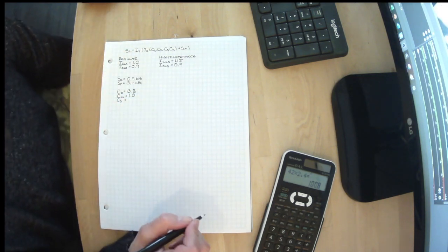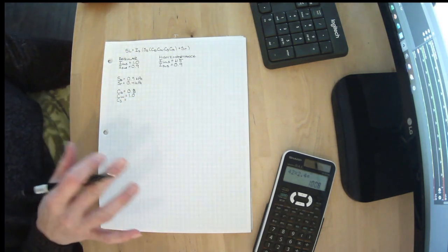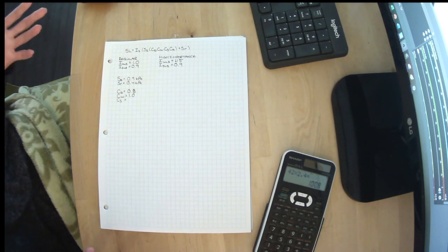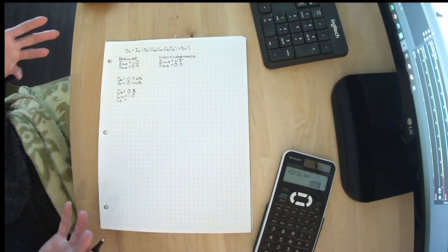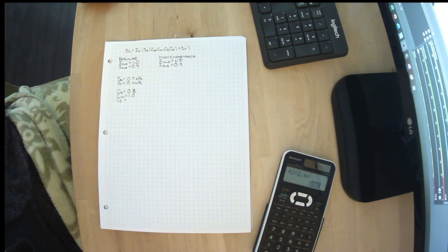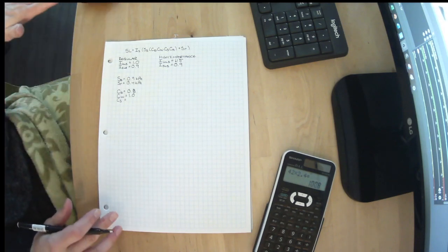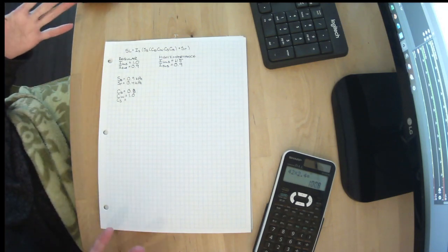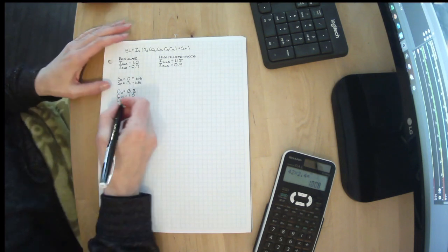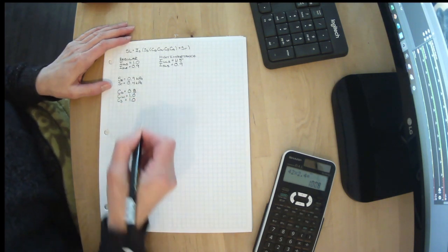CS is the slope factor. That does get used a lot, and depending on your type of roof, you would be able to make good use of that. The building we're doing has a flat roof, so we know that we don't have any slope, which means we don't get any reduction in the snow load.